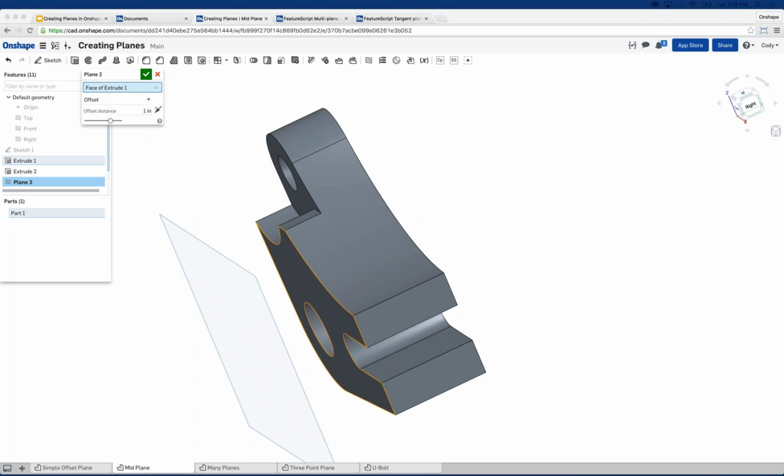The question: if I draw something on a plane that I made, is it possible to change the plane in SolidWorks? You can change the reference of the sketches to a different plane. Forgive me if I'm misunderstanding the question. You can change the reference to the plane. You can edit the plane later, and it will rebuild accordingly. So I believe the answer is yes, assuming I'm understanding the question correctly.